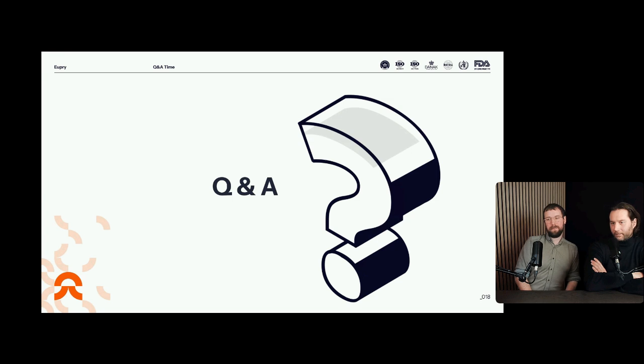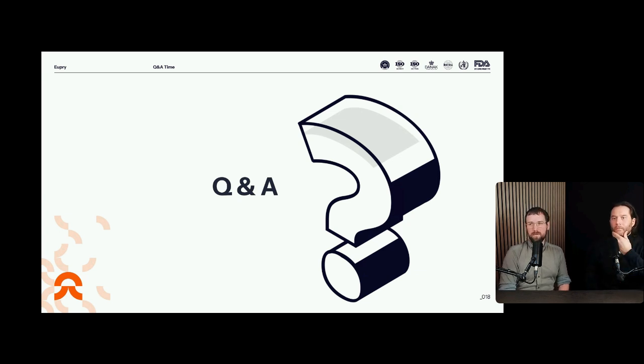Maybe we have time for the last one. Yeah, let's do the last question here from Fogg. We're currently planning a temperature mapping of a few freezers, and there are a lot of discussions regarding where to place our sensors on the shelf. The theory is, if placed too close to the sides, the airflow can alter the temperature profile, and we will get cooler readings. How far from the side and back plates must the sensor be placed? That's actually back to, I think it was Finn who mentioned it earlier, that you need to place sensors where your products are placed.